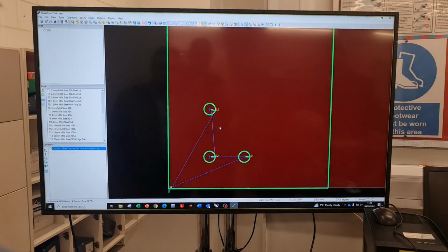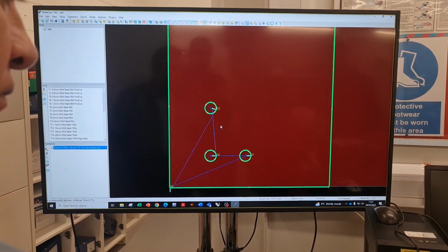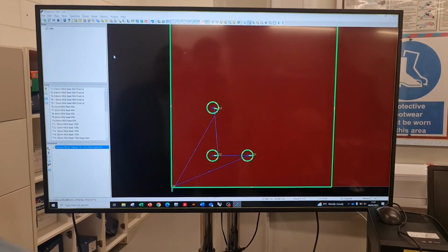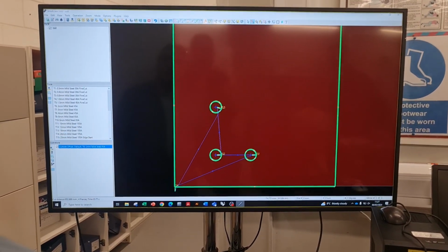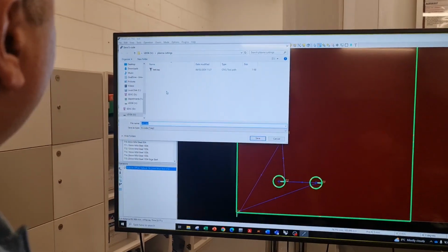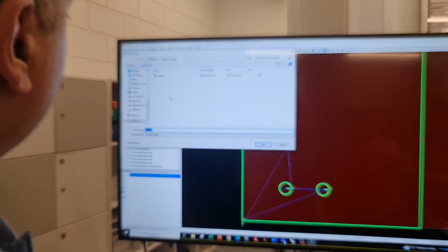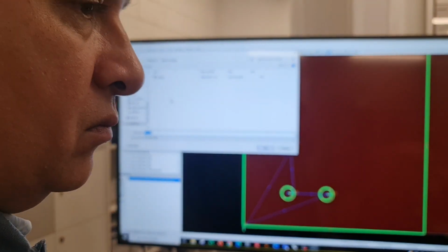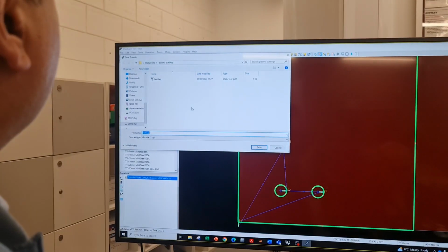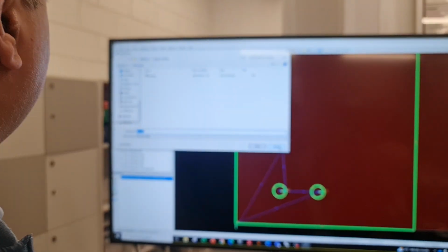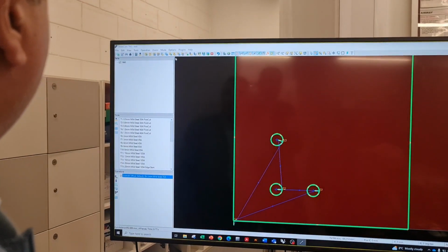At the moment, I already know that there is a fault. When we run the post processor, it generates a .tap. I'm not sure the machine can open a .tap, but I'm sure it should be .txt. Okay, so I'm going to fix that.